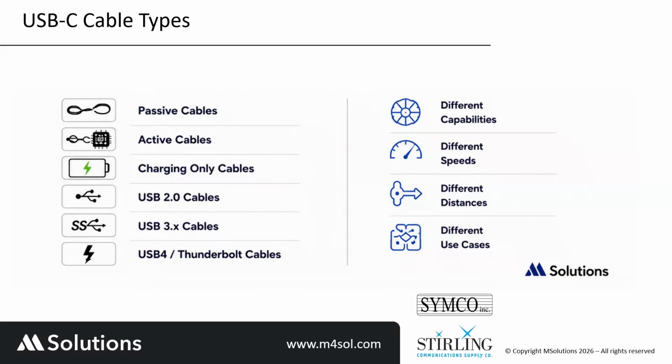USB 2.0, USB 3, USB 4, and Thunderbolt cables each support different data rates, bandwidth, and feature sets. That means we can see cables for Thunderbolt that do not meet the USB 3 requirements. Even though it doesn't sound logically correct, yes, there are cables that support only Thunderbolt and not USB 3 or USB 4, which is supposed to be the equivalent of Thunderbolt.